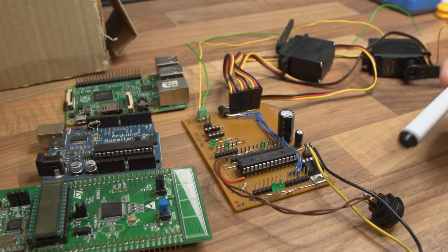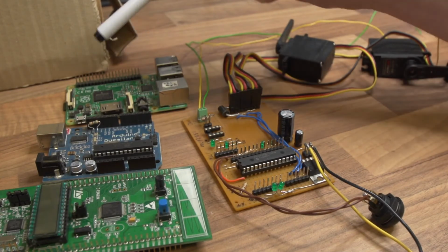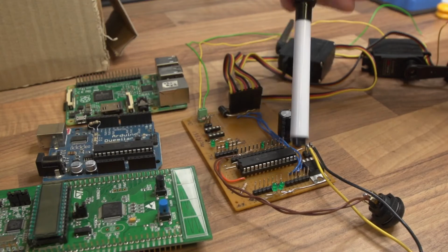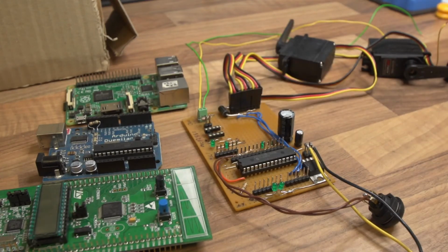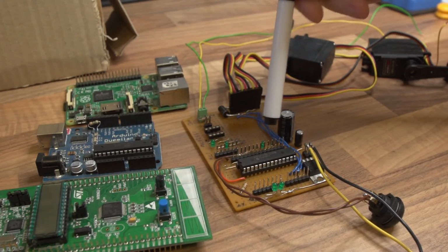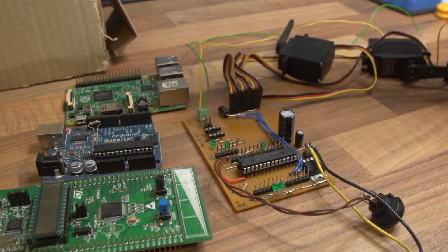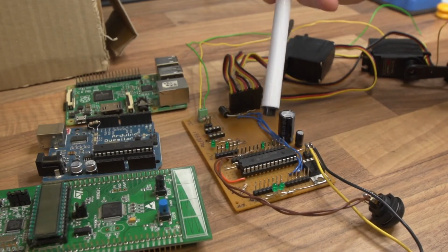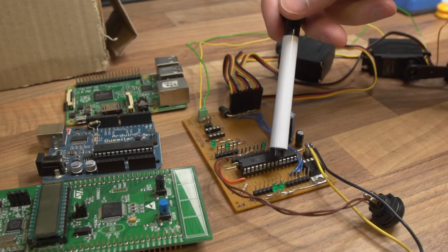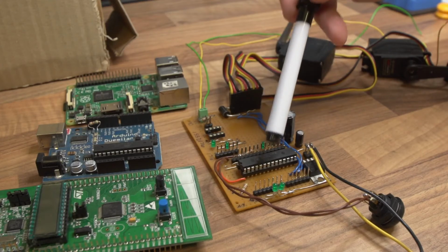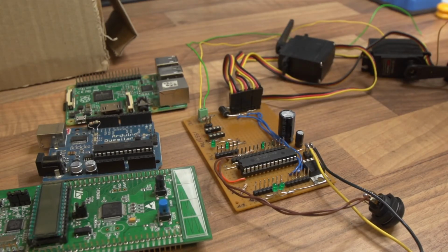And if you look back at the first part of the video, you can appreciate there's a heck of a lot of circuitry inside each one of these microcontrollers. You've got the entire microprocessor device, the RAM, the ROM, the in-out, and other things as well. Sometimes they've got built-in temperature sensors inside the chip, where you can monitor how hot the chip is getting, and you can report that back in real time, for instance. They've got warning detectors, like if the supply voltage goes too low, it can self-detect whether it's going to have a problem before it happens. So you could report back if there's going to be a problem with the supply voltage. All kinds of things like that. What they call brownout detection, and it's all built in.